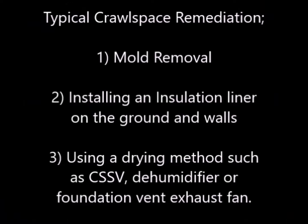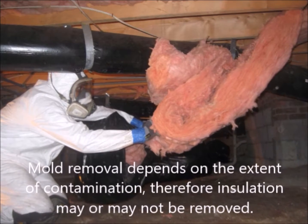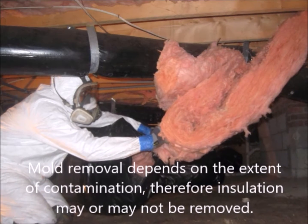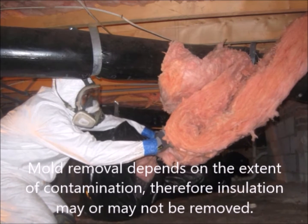The typical crawl space remediation consists of mold removal, installing an insulation liner on the ground and walls, using a drying method such as a crawl space supply vent, dehumidifier, or foundation vent exhaust fan. Mold removal depends on the extent of the contamination. Therefore, insulation may or may not be removed.